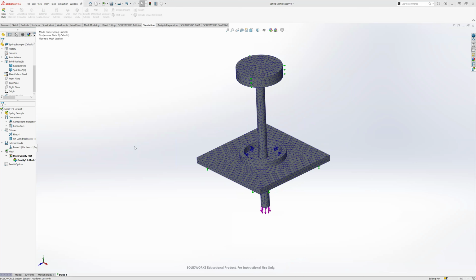And it's going to give us kind of not an error necessarily. I'm not sure if you actually can see this because of the way I'm sharing this. But if you can't see it, I'll read out what it says. It says excessive displacements were calculated in this model. If your system is properly restrained, consider using the large displacement option to improve accuracy of the calculations. And then it goes on with a bunch of other stuff.